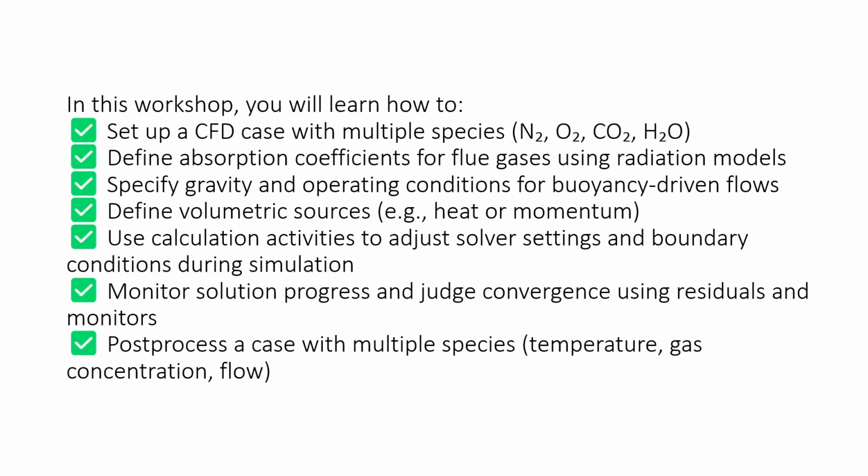How to activate gravity and set up operating conditions to properly capture buoyancy effects, which are essential when modeling hot gases rising due to fire. How to define volumetric sources like heat or momentum directly in the domain, for example, simulating the heat released from a burning engine. How to use calculation activities to dynamically change solver settings and even boundary conditions during the simulation. This gives you advanced control over how the case evolves.